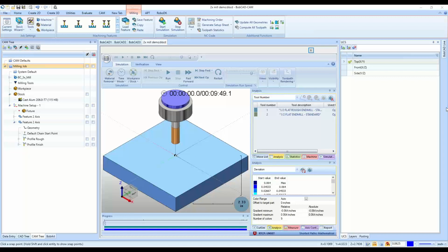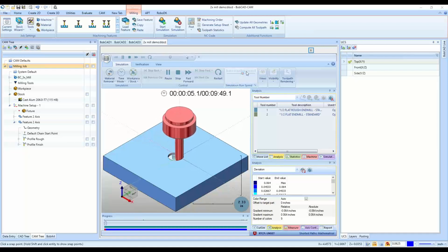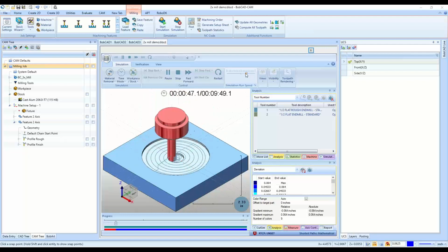Bob, can the default depth be changed? Yes, I believe I went over that. It is set up by default for a depth of 1/2 inch, but if you saw the top of feature highlighting those boxes, top of feature, and then selecting the top edge of the stock, or top edge of the feature, and then bottom edge of the feature, it automatically sets up the depth that way. And you can also manually change it if you know exactly what it is.